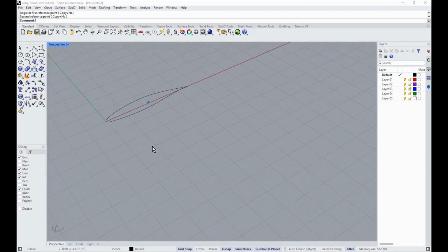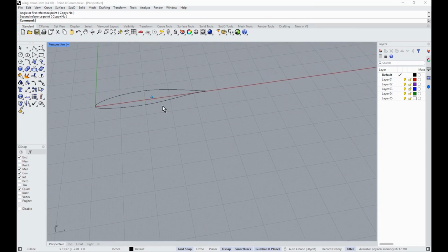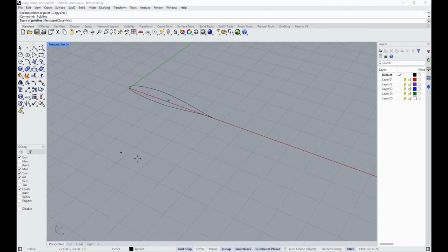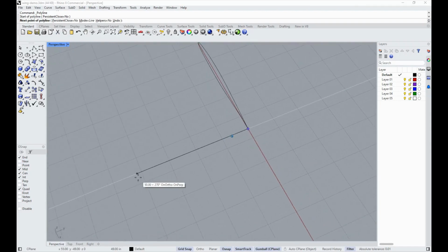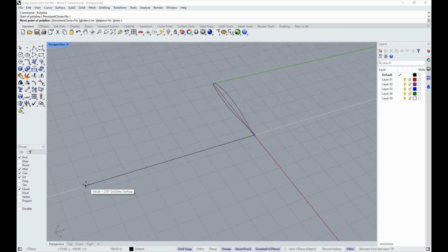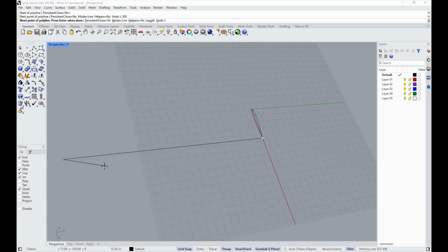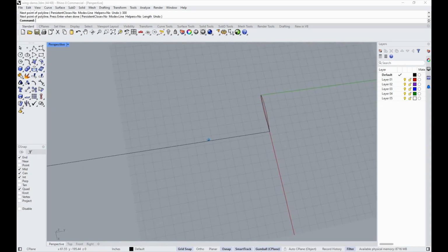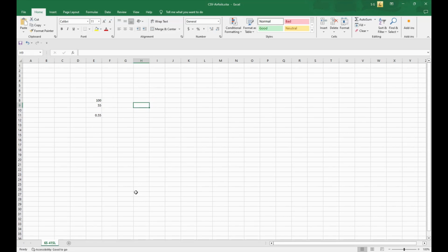So let's just say that we want our tip to be like 30 inches or something like that. And we're going to set this straight out. So let's go grab a line. We're going to make a scimitar wing, just like the Bronco 3D CAD file. So I've clicked on the trailing edge. I have a line. I'm going to press 300. And now it's going to act, yeah. So just send it in that direction. Right click, it ends it. Of course, that's kind of huge. Let's do some simple math here, like a 25-foot wing. So we're going to do 25 feet.